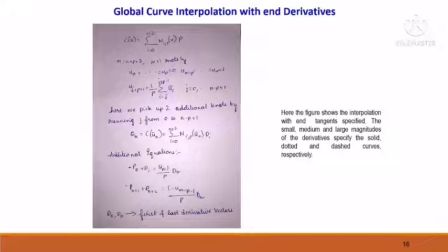And again, let qk, that is k equal to 0 up to n, be points, and assume d naught and dn are the first and last derivatives, and we want to interpolate this data with a degree p curve, that is C(u) equal to the sum for i equal to 0 to n plus 2 of N i,p(u) P i. Then we compute the uk, k being 0 up to n. We compute this using the knot vector and the parameterization equations, and then we set m equal to n plus p plus 3, and then we obtain m plus 1 knots by using this formula.